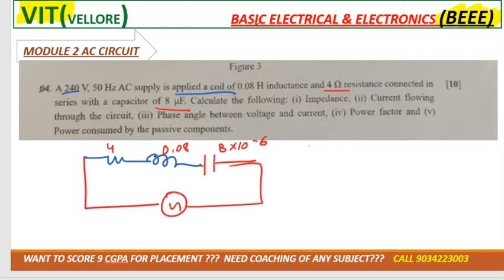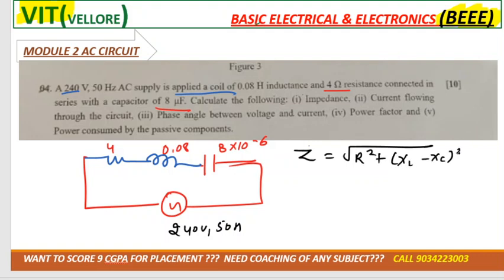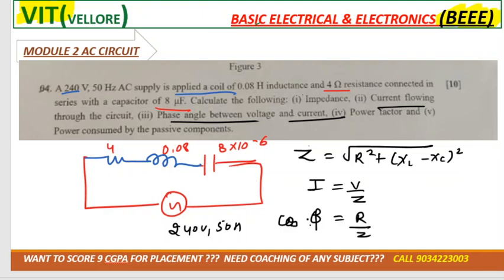Calculate the impedance. Voltage is given as 240 volt, 50 hertz. Now you can get impedance, that is root of R squared plus XL minus XC whole square, right? Then you need to calculate current. Current is V over Z. Then you need to calculate the phase angle. Phase angle is phi, and cos phi is R over Z. Then phi you can get in a similar way, cos inverse of R by Z, right?